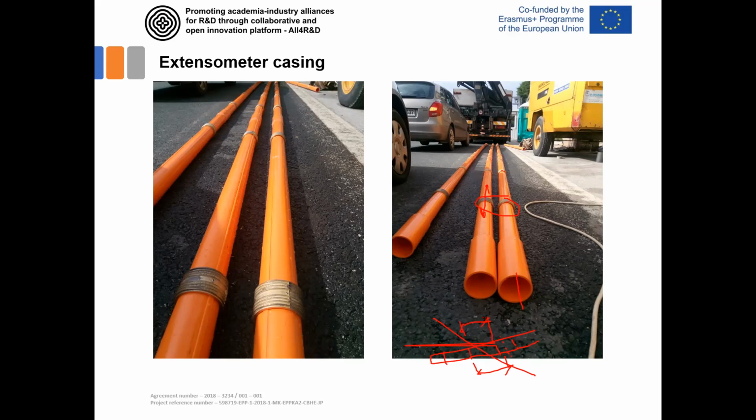More often in local practice, inclinometers were used, a vertical hole with plastic pipe grouted all around. But the principle is different. Here you have these magnetic rings, because they can be recognized by a special probe that you enter into this pipe, same as the inclinometer probe that is inserted in the inclinometer casing.